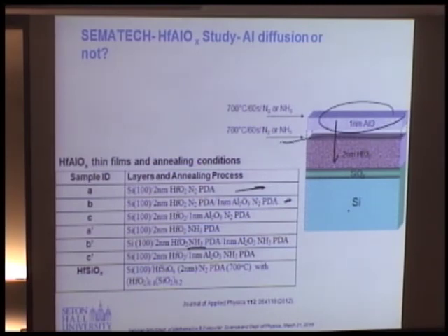You do some kind of annealing, nitrogen or ammonia annealing at this condition. Then it kind of toughens the surface and creates a block layer. And then if you put the aluminum next, there's no diffusion. And you don't disrupt the crystal structure here at all, okay?